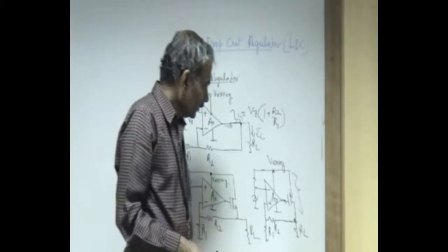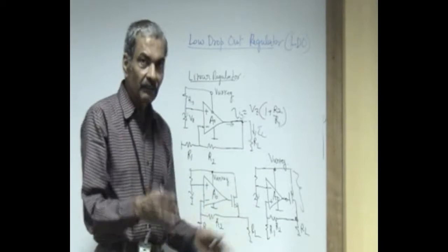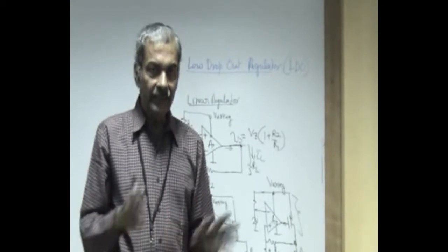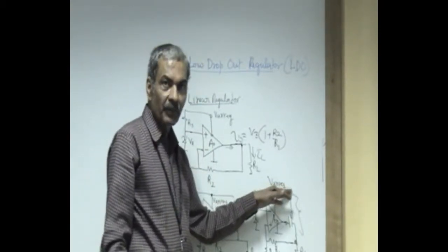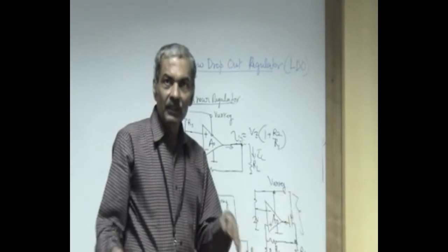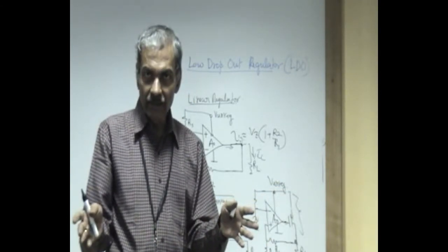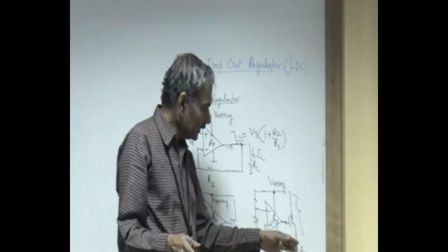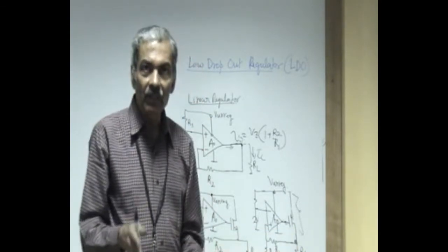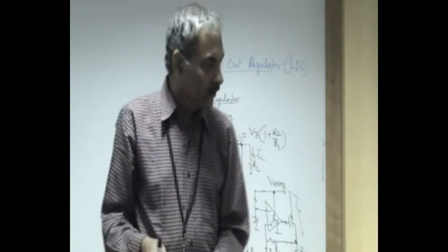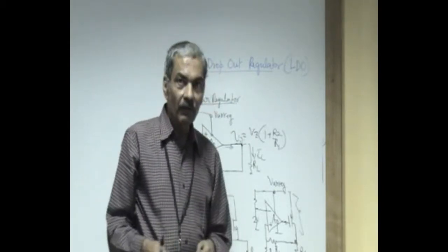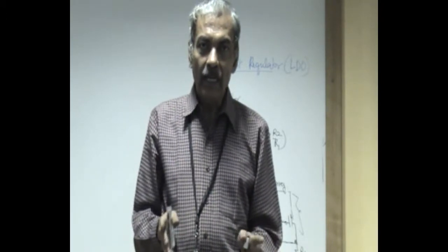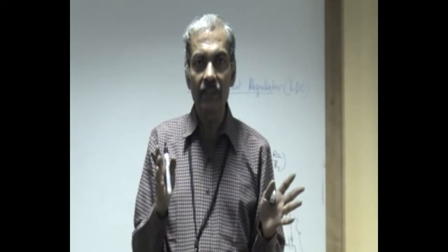Right? So you make sure that you make all the measurements of load regulation, line regulation, ripple rejection. Again, you assume that there is a ripple superimposed over the unregulated supply, which is normally at 50 Hertz or 100 Hertz if it is coming from the power line. Okay, and then how much of it gets transmitted to the output? That is what is called ripple rejection factor. Right? So make the measurement of all this. Ripple rejection is a small signal parameter. Output impedance is a small signal parameter, and the line regulation and load regulation are large signal parameters.